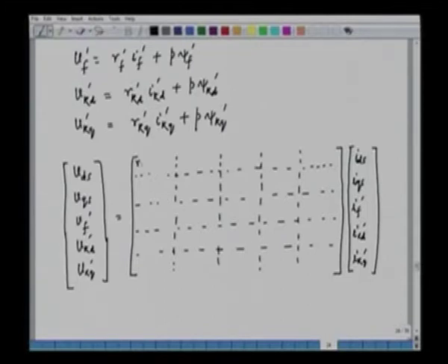Now, this is the stator resistance drop plus the self inductance drop, LDS, and LDS is equal to LLS plus LMD, and we will have the coupling with the D axis rotor. It is LMD with the rotor, LMD with the D axis damper, and then we have the rotationally induced EMF. This will be minus omega r into LQS. This is minus omega r into LMQ.